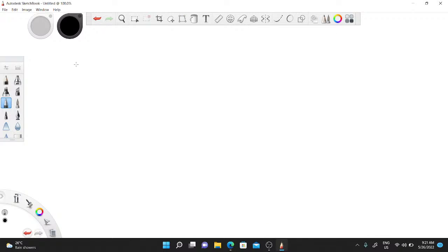So I'm having a generator here. This generator has power 100 megavolt amps, voltage 33 kilovolts, and a per unit reactance of 0.15. It is connected to the motors through a transmission line and transformers as shown in the figure. So you can see the figure there.